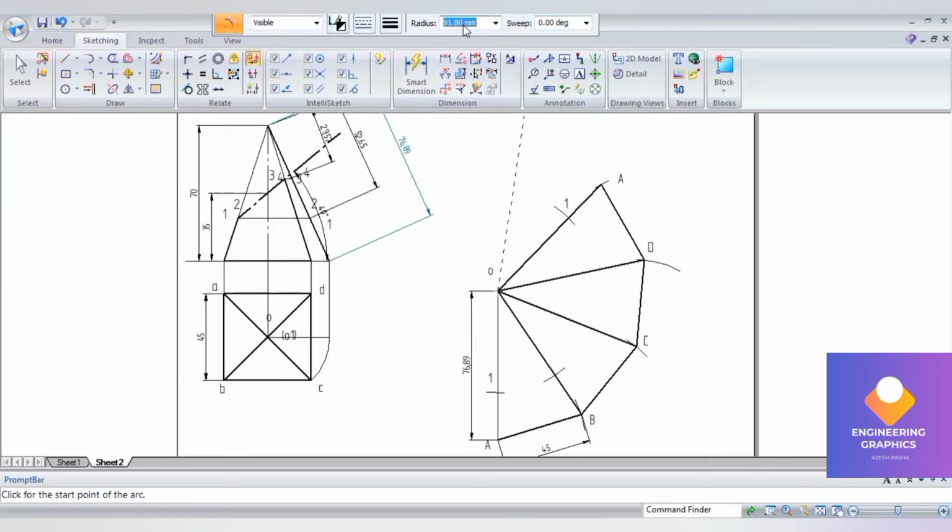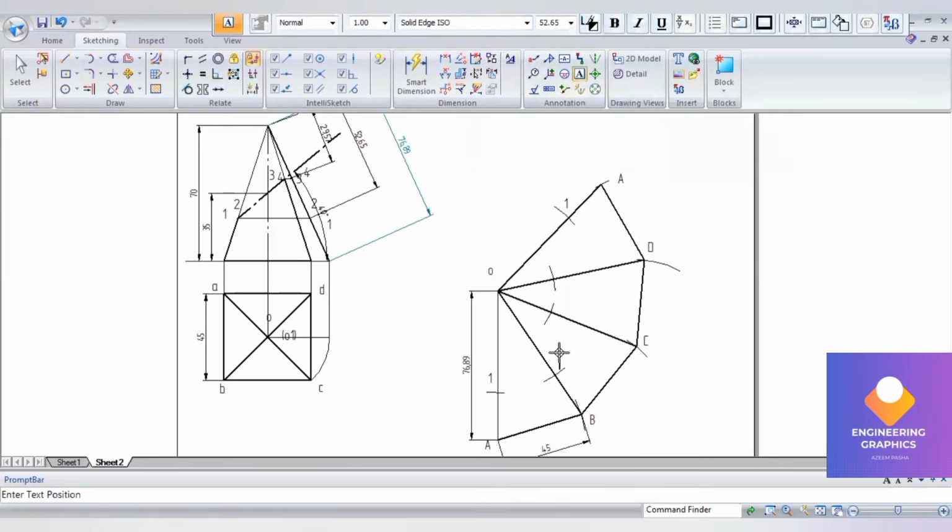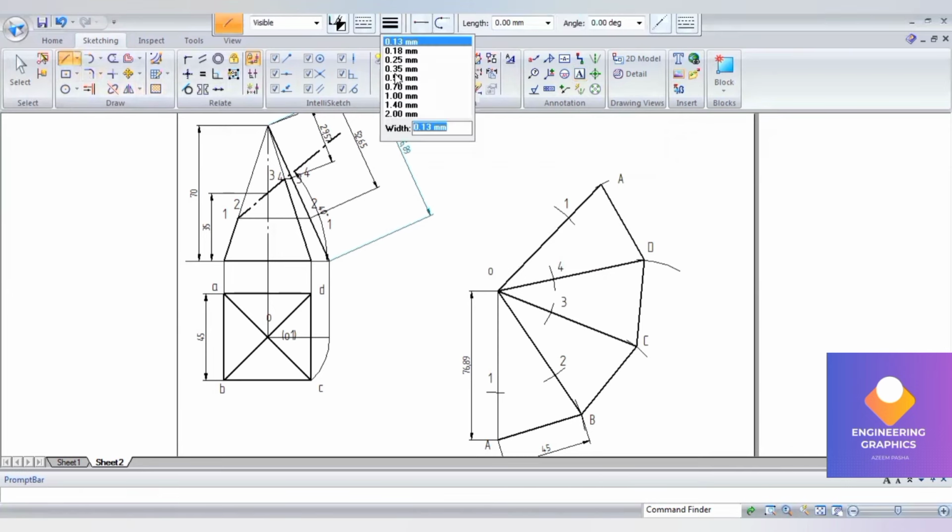So that is your arc point 2. And then on OC and OD you have to give the same length, that is 29.57. Okay, again on the OD also we have to mention the same length here, 29.57, cut it. I can mention the namings of it here, 2, 3 and this is 4. Now we have to join all these cut points here with the thick line.